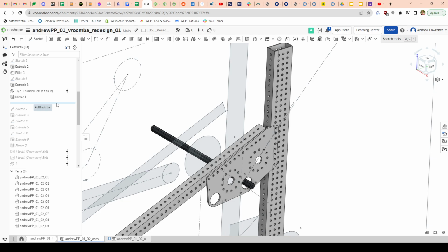When I say properly modeled, I mean modeled in a way where you can change the file or change the dimensions or change your model, and the shaft will update properly. There's the easy way of making the shaft, which is select a point and blindly extrude and then just keep updating that. And that was the old way.